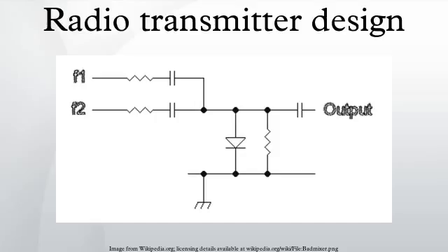Plate AM modulators. High-level plate modulation consists of varying the voltage on the plate of the valve so that it swings from nearly zero to double the resting value. This will produce 100% modulation and can be done by inserting a transformer in series with the high voltage supply to the anode so that the vector sum of the two sources will be applied.